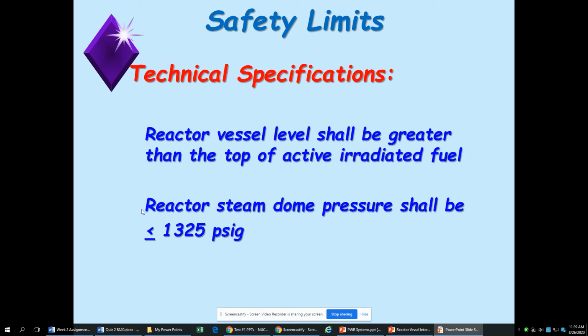So both of these are kind of like the law of the land. You can see this big shall in here. That's always a scary word, and it's a government word, right? The NRC had us put this word in here. So if that water goes below the fuel, we're shutting the reactor down indefinitely while we go in there and take a look at all the fuel and make sure that none of it was able to melt. And the same thing here. If we get above this pressure, we're going to shut down and make sure everything in the reactor is still working correctly.